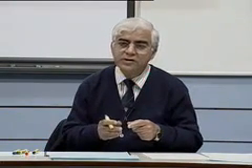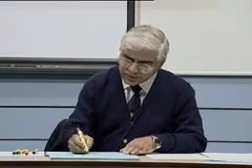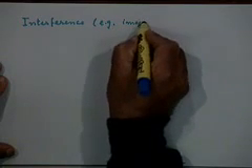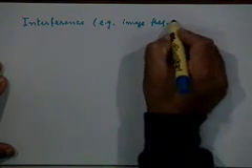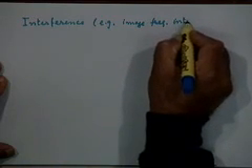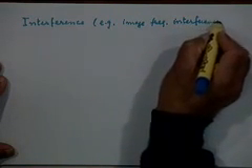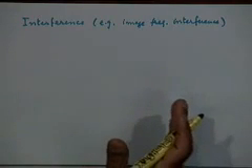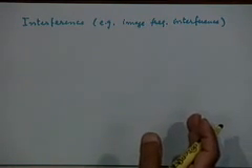you have a desired signal, a modulated signal around the frequency omega c. Along with that we get an image frequency component. If your RF filter is not good enough, that is likely to happen. So for example, it could be the image frequency component. Of course this will not happen if your RF filter is designed to reject at least the image frequency.